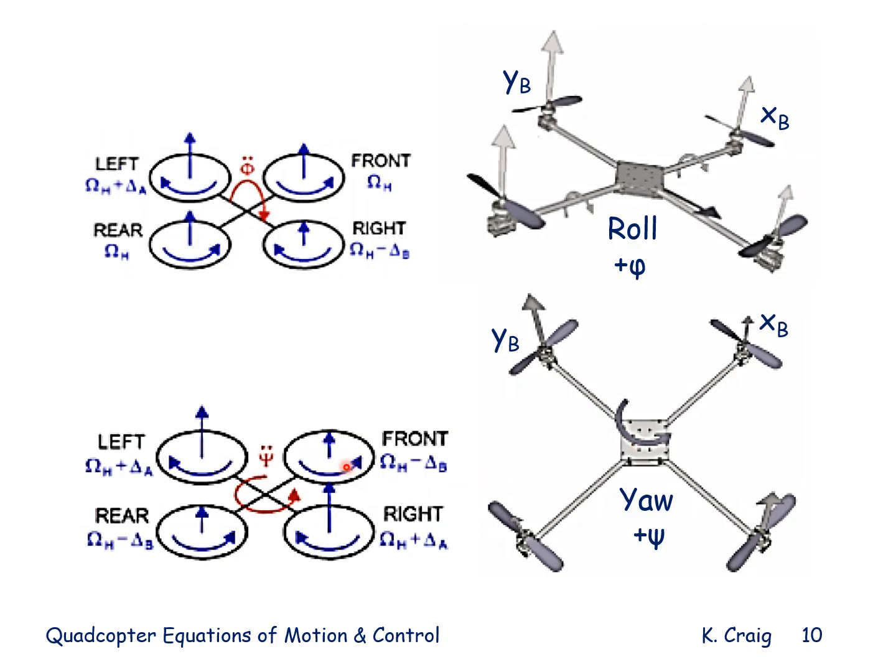And since motors 1 and 3 rotate in the counterclockwise direction, which means that they impart a clockwise torque or moment to the quadcopter frame about its positive z-axis, we then need to reduce that reaction torque on the quadcopter, and so we reduce the speed of motors 1 and 3.